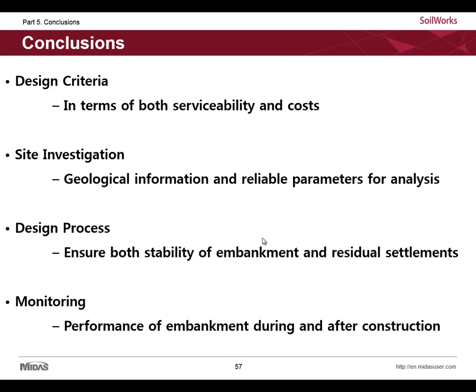Finally, monitoring during and after construction. Nobody can predict exactly what's going on during and after construction. Sometimes we need to do a back analysis with more appropriate design parameters during construction, or have to design additional reinforcement methods after construction.